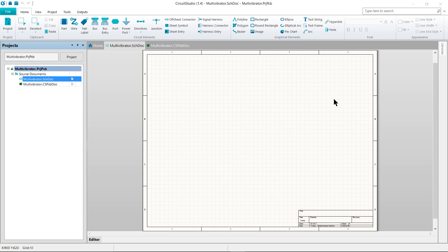First, let's go ahead and make the Altium Content Vault available to us by making sure we are connected to it. You do have to be online for access to the Altium Content Vault. If you do not have online access, you should be able to locate similar parts within the default installed libraries. However, this particular tutorial will focus on the use of both the default libraries and the Content Vault.